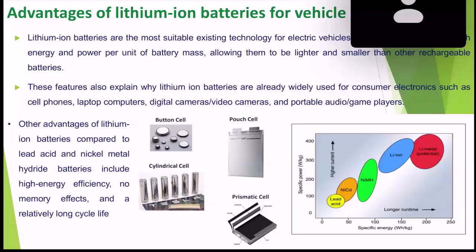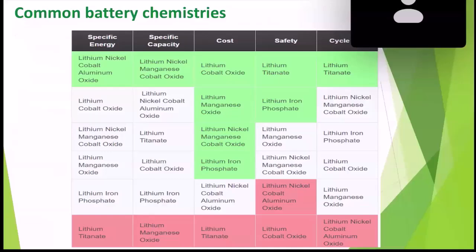But in the case of the recently launched BYD vehicles and Mahindra vehicles, they use blade type batteries. That is a specific type of battery technology which has been developed. And again in lithium itself, there are 5 to 6 chemistries available with respect to the components used. The metal oxide components used in one type of battery vary from another battery, like lithium cobalt oxide based, lithium titanate, lithium manganese based, and lithium LFP, which is most widely used and cost effective. Each and every chemistry has its own advantages and disadvantages, and depending on this, the characteristic features or property variations, these chemistries will vary.